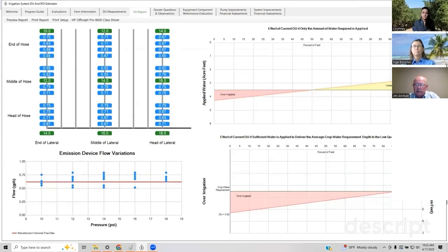They'll continue to irrigate to try and apply water to this under irrigated area. If they do that, which most do, they continue to irrigate to the worst area in the field, you can see what happens. Now we have over 5 feet of water, not 3.5 that we need, applied to this particular area. So we over irrigate. So this is lost dollars provided to produce the energy, water, and also fertilizer.